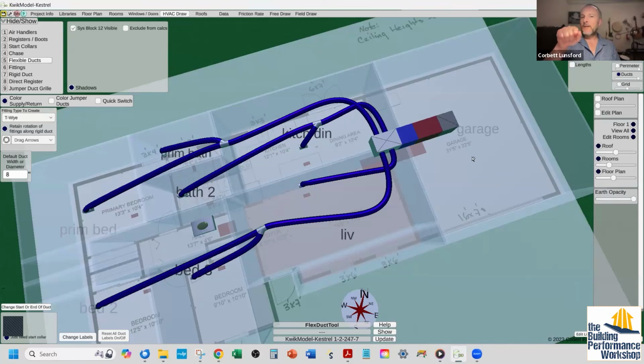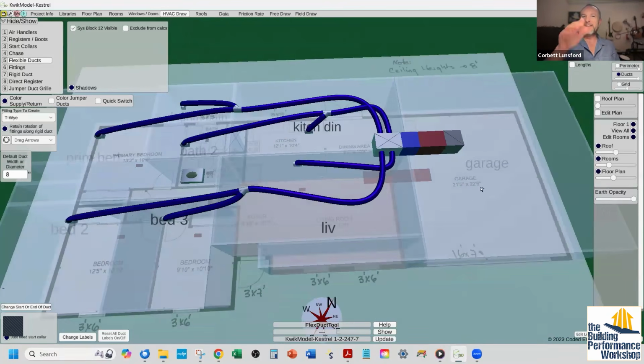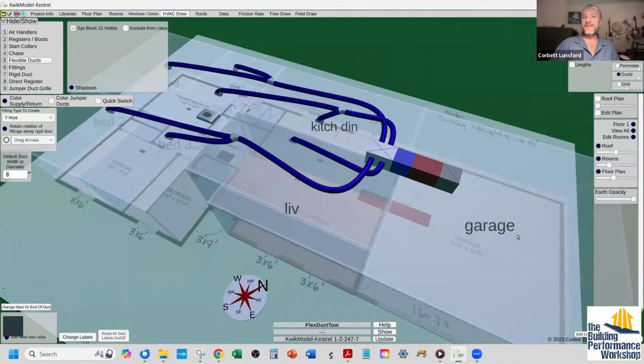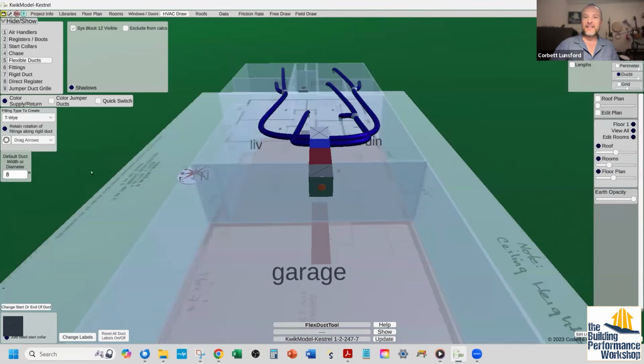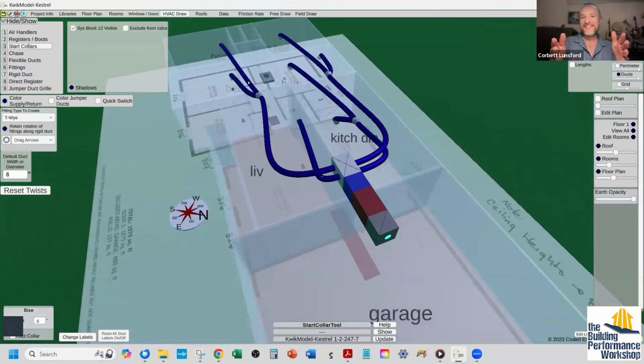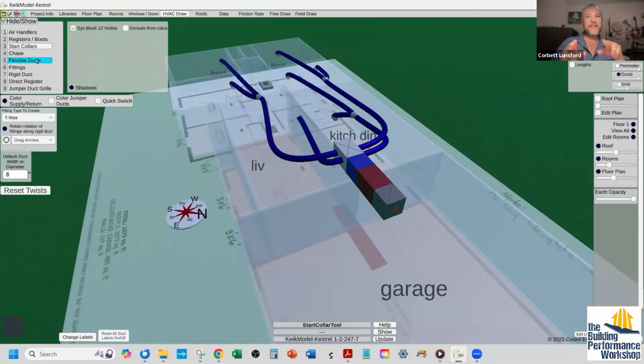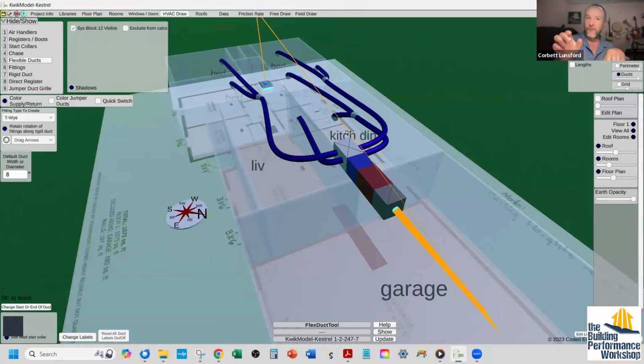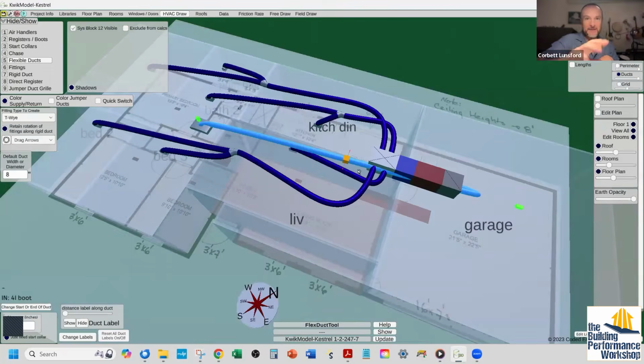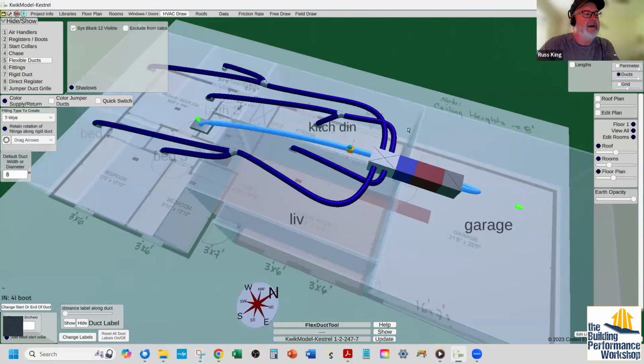Now, Russ, we're at a really dangerous point where somebody's going to stop watching in about 5 seconds, and they'll be like, "Okay, I get it. You just build this plenum, and then you just connect all 6-inch ducts to it," which is what it looks like we're doing here. This is not what this software is actually like. You're going to put in the numbers that are going to then tell it, "Oh, this duct needs to be 4 inches. This duct needs to be 8. This one needs to be 6. This one needs to be 10, etc." Exactly. Excellent point.